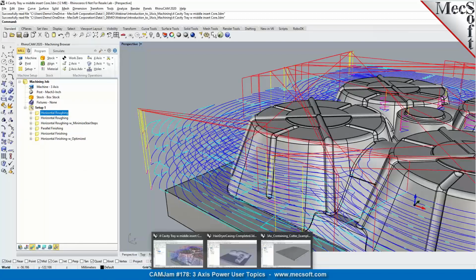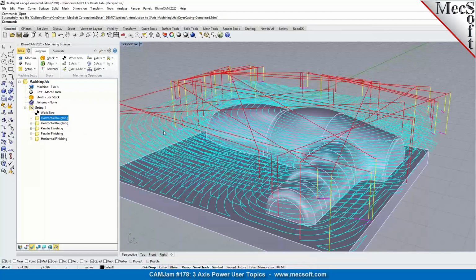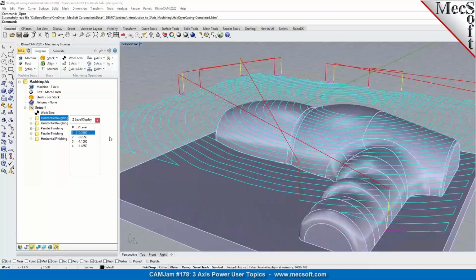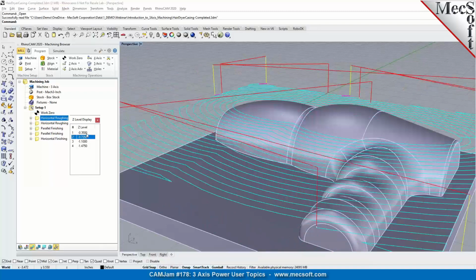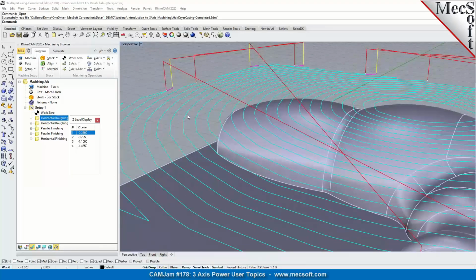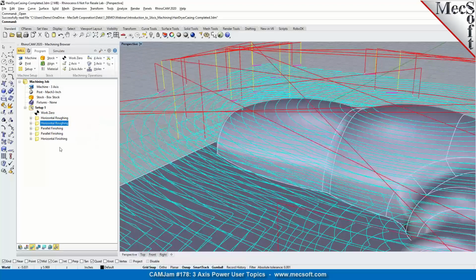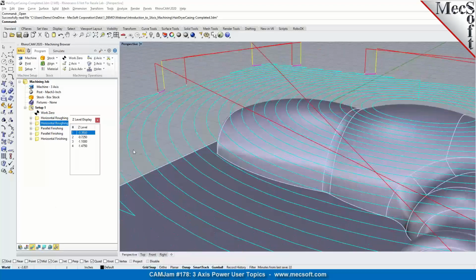Now I do have another example in here where you can see the same effect of tolerances. With the slacker tolerance, you can look at the chord segments are much longer. With the tighter tolerance, it's more accurate and much smoother, resulting in a much finer finish.